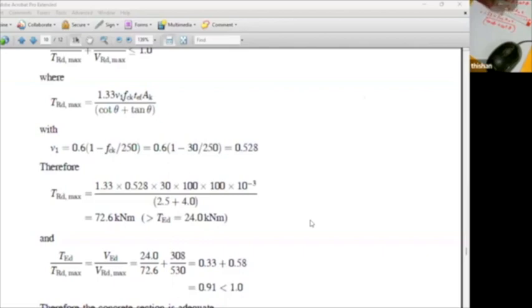If you are designing a transfer floor, there will be many beams where you have to check for torsion. I think we checked over 15 sections for torsion, but we did it for the BS code because it's much easier to check. But again, I did not do the calculations manually. I did all the calculations using a computer program.